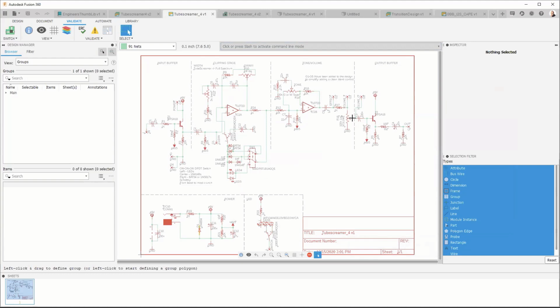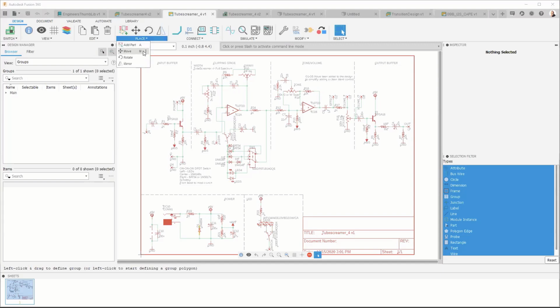In Eagle, you could use the assign command, and you would define these combination shortcuts. You would have a modifier and usually a letter, and you would assign a command to it. In Fusion 360, most of the commands already have shortcuts defined, and these are single key shortcuts. For example, the add command is A, move is M, and under connect, net is R, etc. Now you may be saying, I like having the ability to define my own shortcuts. And for that, we have the S menu.